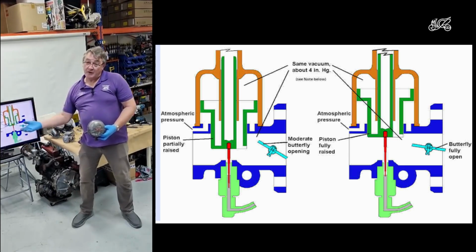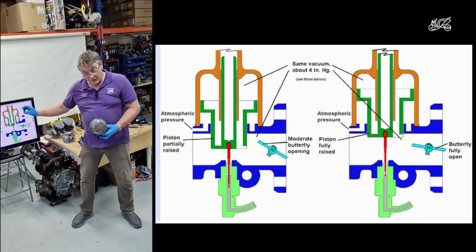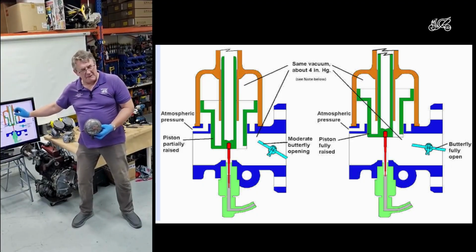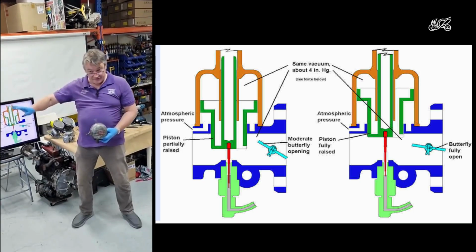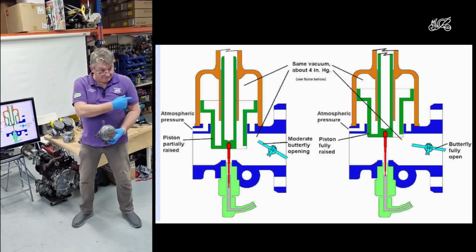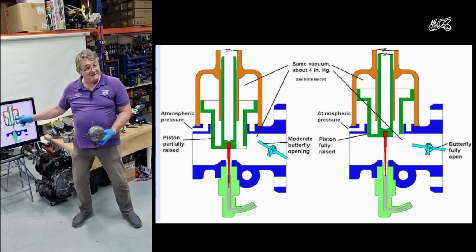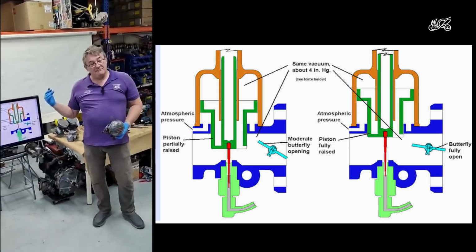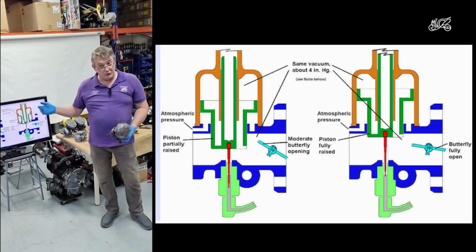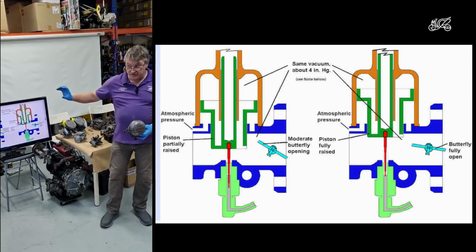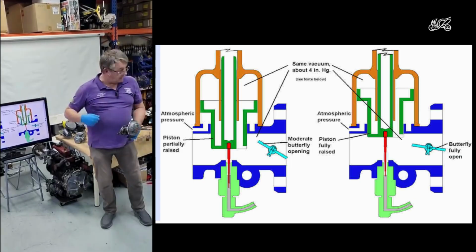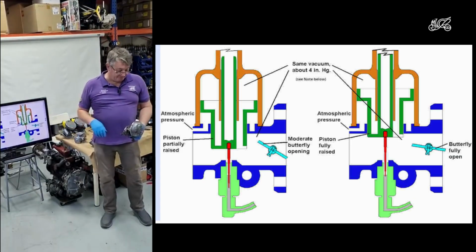It's going to take some time for the piston to rise up. And whilst it's flowing through the small space, the pressure drops because it has to move faster, back to the basic principle. So it sucks more fuel out. So you've got the enrichment caused by the fact that you restrict the choke when the airflow changes and you accelerate.